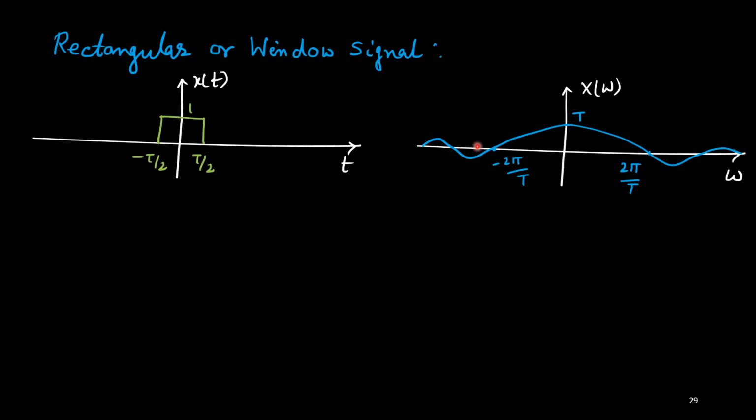So now I'll show you one more important thing. If I consider this width is small, then this is the shape, because it will cross this one, sine omega capital T by 2. So the sine function will become 0 when it is sine of pi, 2 pi, 3 pi, like that, sine k pi. Okay, so the first zero crossing point will be when sine omega capital T by 2 equals pi, meaning omega equals 2 pi upon capital T.